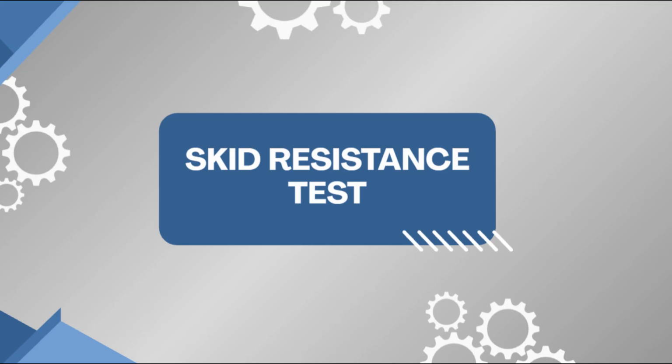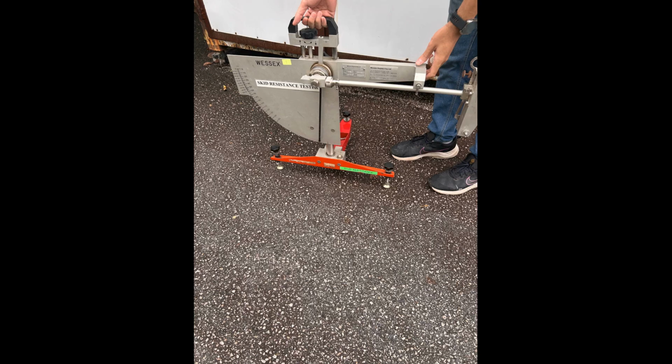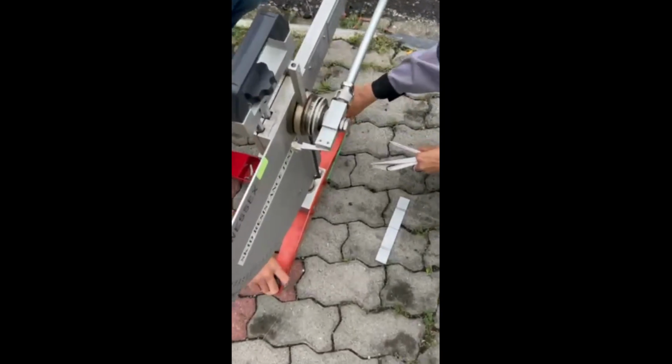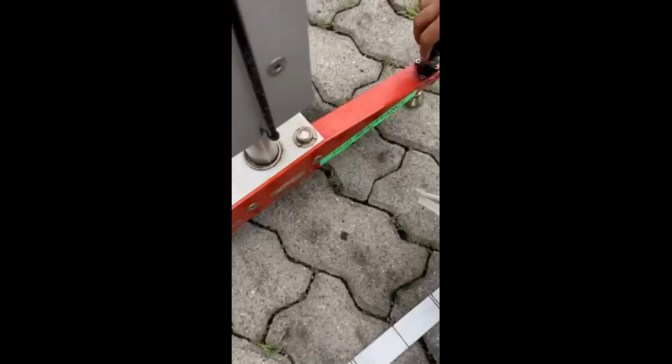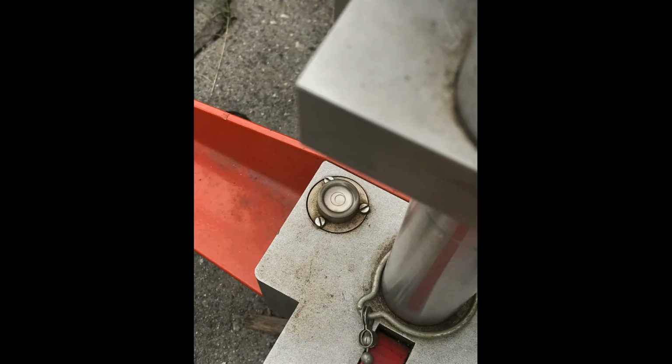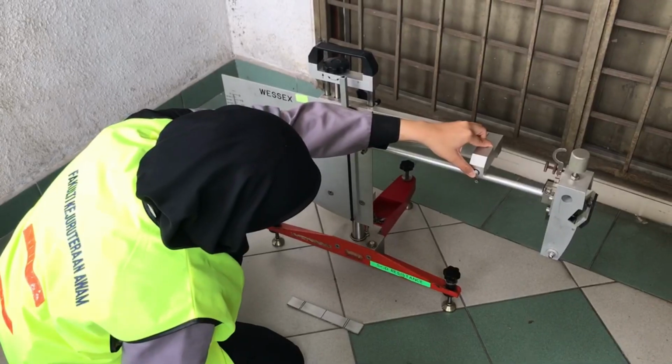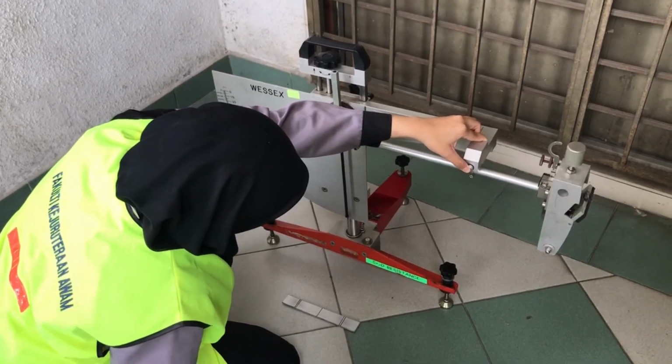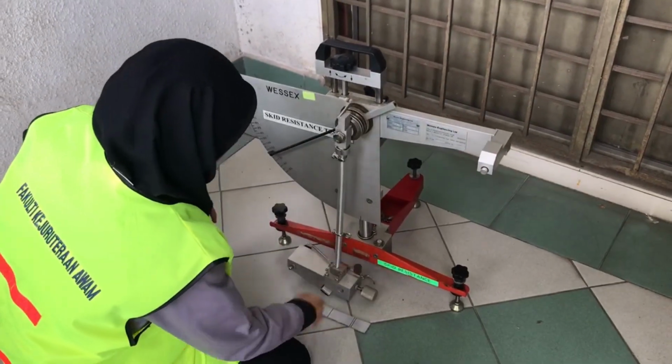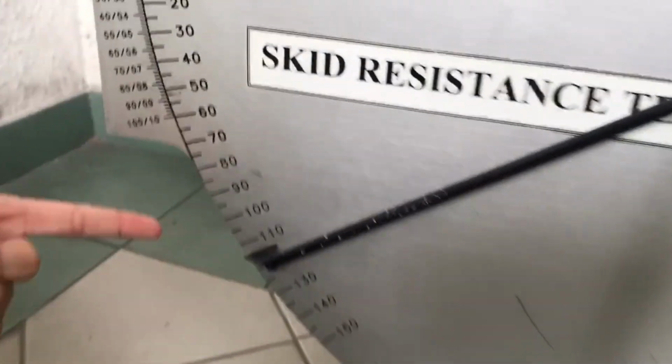The last test conducted is the skid resistance test. Step 1. Equipment setup. The British Pendulum Tester, BPT, is placed on the test surface. Adjust the spirit level bubble until it is perfectly horizontal and level before use. Step 2. Zero calibration. The pendulum is released without touching the surface. The pointer should read 0.